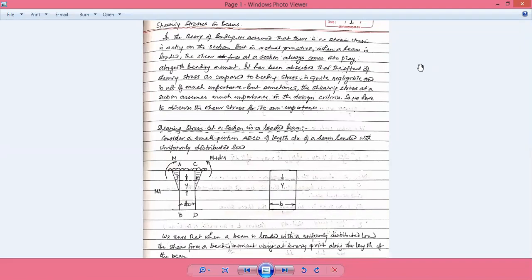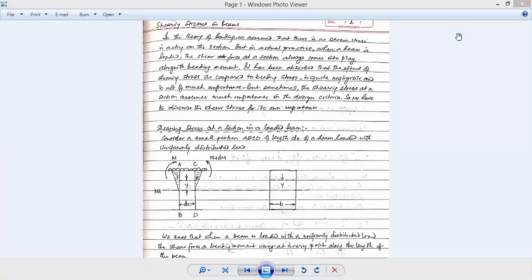First, we know we have to use the bending moment across different sections of the beam itself. In the process, we deduced a bending moment equation which gives us the bending stresses induced in different sections, which depend on the induced bending moment across all these sections. In that particular lecture, we discussed the bending moment across two adjacent sections, which are away by an elemental distance like dx, meaning almost the same section but not exactly the same, they are away by an infinitesimal distance.